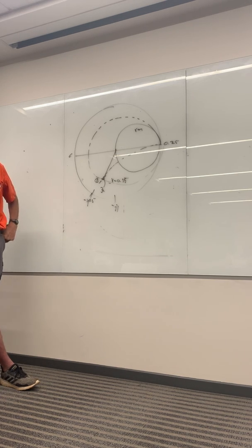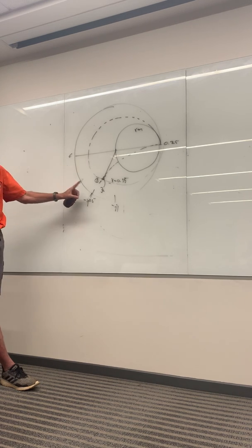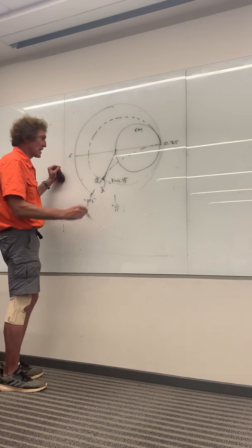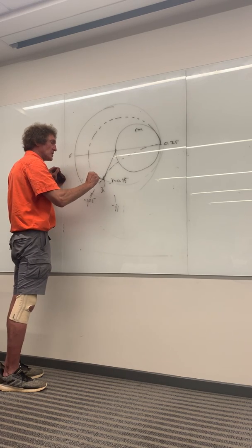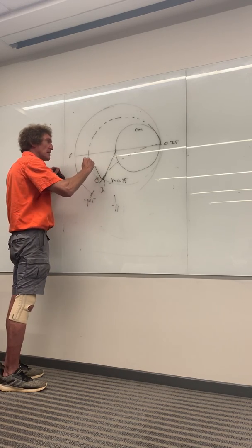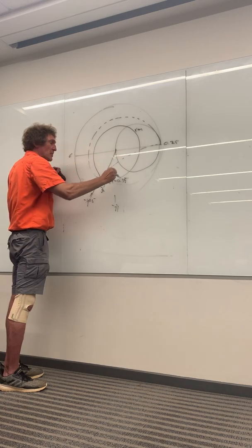Remember, it's down here in the lower hemisphere because of that minus j. It's minus j0.5, all right, that's zL. And now take that and use your compass and make a circle with that radius.